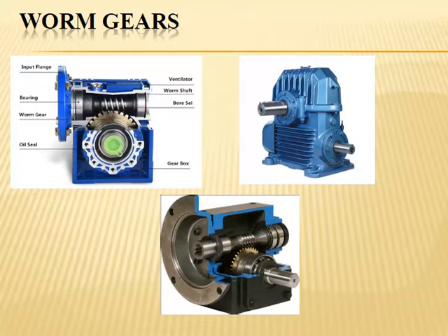Adequate lubrication is necessary for satisfactory performance and durability of the worm gear pair. Inadequate lubrication contributes toward scoring failure. Adequate lubrication means adequate quantity and quality of lubricant, properly circulating inside the gearbox.